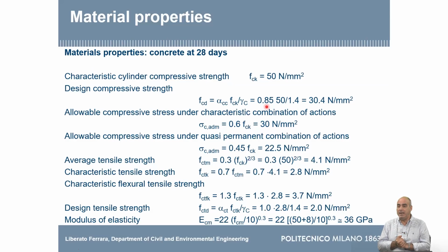But what has been experimentally observed is that if you apply this stress and keep it constant, and this stress is higher than 80–90%, depending on the class of concrete, you will experience what is called a delayed failure. So at a certain point, your concrete will continue to creep, but at a certain point, it will break. So in the long term, it's like if your strength will be lower.